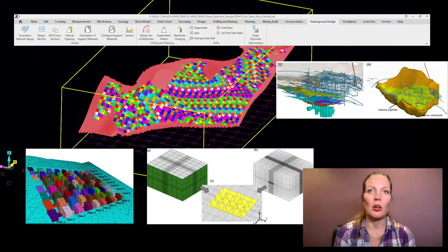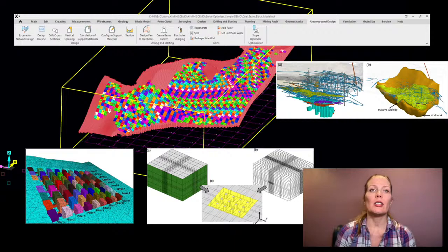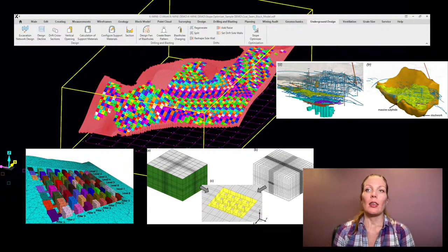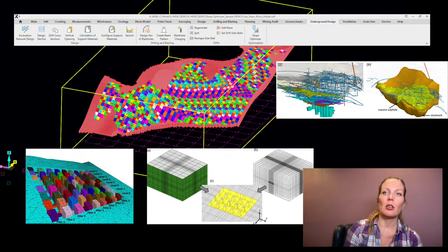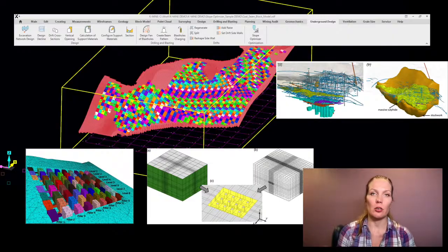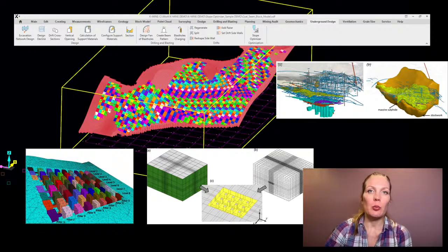The second common scenario appears in stratiform, gently dipping, or otherwise well-organized deposits where the mine relies on a regular room and pillar development pattern. In this case, the mistake usually goes in the opposite direction. The optimization is run on a standard cubic block grid without considering the mine's actual discretization. The result is an irregular stope outline that in some areas pushes into future rooms, in others cuts across planned pillars, and elsewhere carves out thin slivers that have no practical place underground.